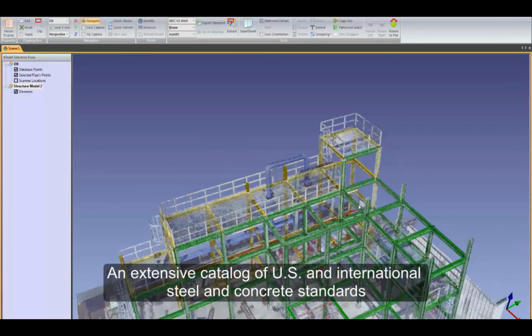Then the wave will bounce and come back to the equipment, to the radar. And of course, the propagation speed of this wave will depend on the material that it has penetrated. Whenever it goes across another kind of material, for example, pipes, it will have a different propagation speed.